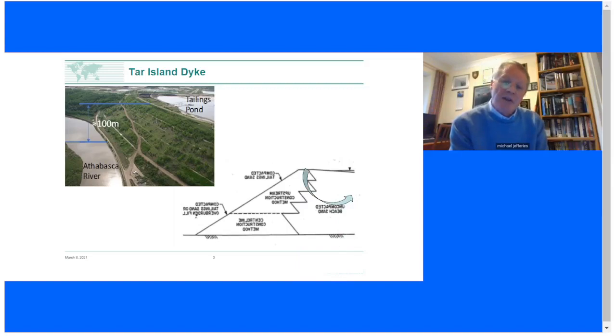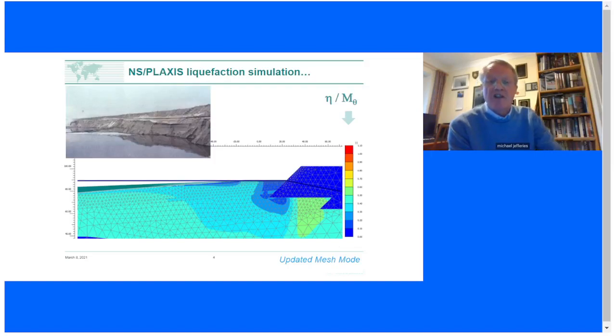The nice thing about these slumps is that you can treat them almost as test loadings, because it's a very simple geometry and a very simple crest load being applied. There's no funny foundation behavior. There's no funny water pressures. It's a very simple loading geometry. And so it makes a lovely test case for us to say, okay, can we understand this drained to undrained transition?